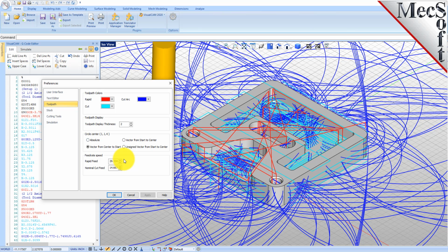That's an extensive change. So what we're doing here is we're just matching what's in the G-code file so that they display properly. If you see this on your controller, you need to go back into the CAM module and adjust your IJK format settings in the post-process generator to match what your machine controller is expecting to see.